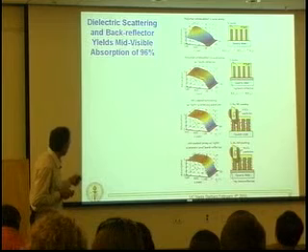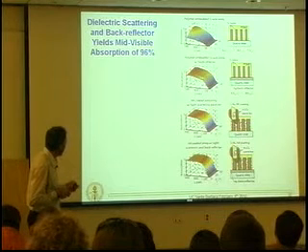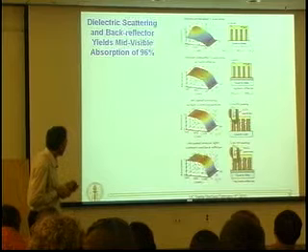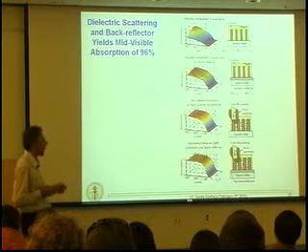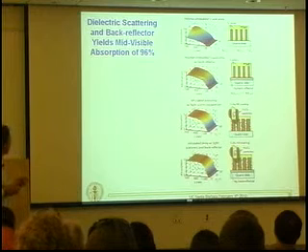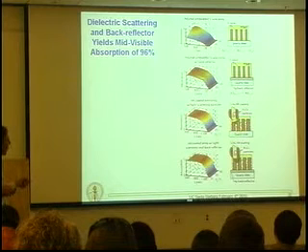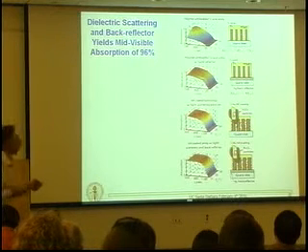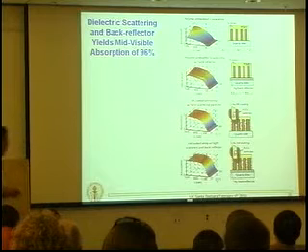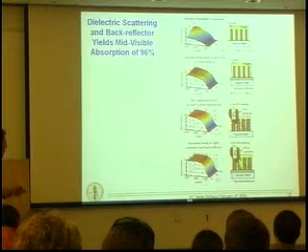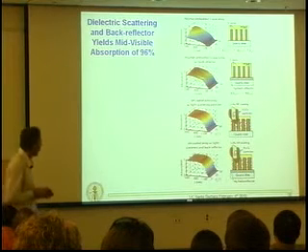increase the absorbance here, and so the mid-visible spectral absorbance is as high as it is for the best quality silicon solar cells. It's about 95%. And these are wire arrays whose volume fraction, equivalent to a wafer of equivalent thickness, is 4%. In other words, this is a polymer sheet embedded with a parallel array of wires, where the silicon volume is 4%.